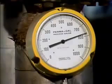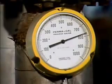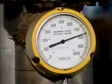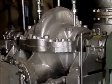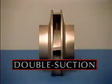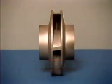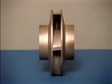In applications where the pressure change is higher, large amounts of axial thrust are created and must be offset. To minimize the effects of the axial thrust, some centrifugal pumps use a double suction impeller. A double suction impeller has two suction eyes, so liquid can enter the impeller from opposite directions. Because of this, the pressure on both sides of the impeller is the same, and axial thrust is minimized.